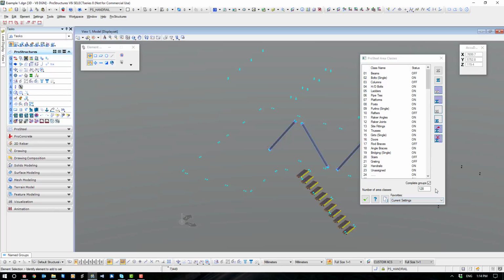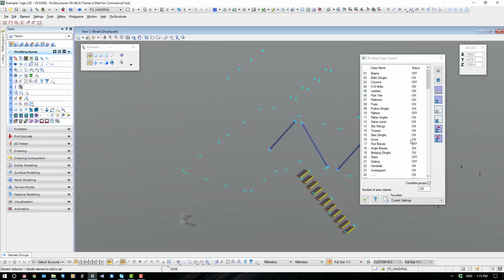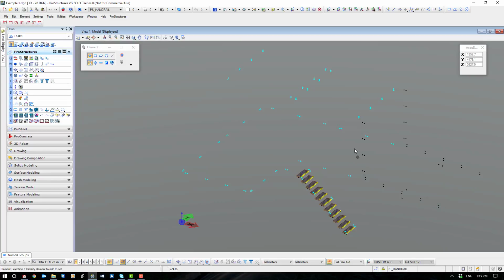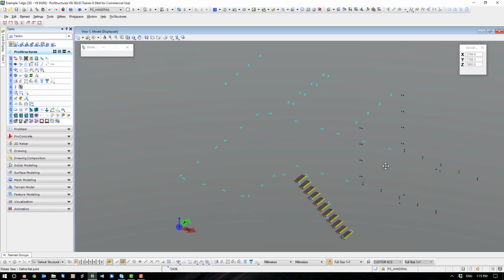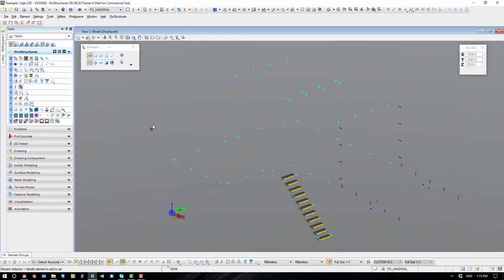very good. So what we'll end up with, and the complete groups, make sure you leave that ticked on. I've mentioned that earlier, but just don't ever tick that off by accident. Okay, it's just pipe ties, which are hollow ties. Okay, and what we've got left now is we've got some grading for the step treads, and we've got the 8.8 bolts, and we've also got those structural bolts for the handrail.